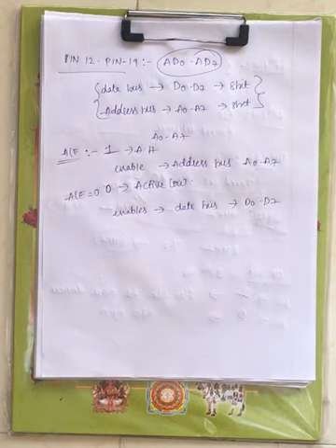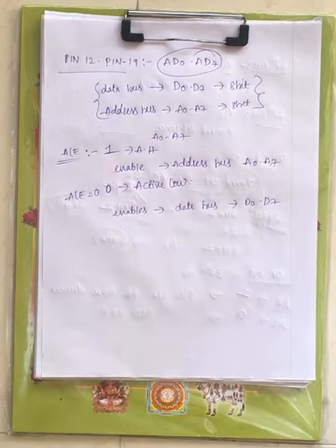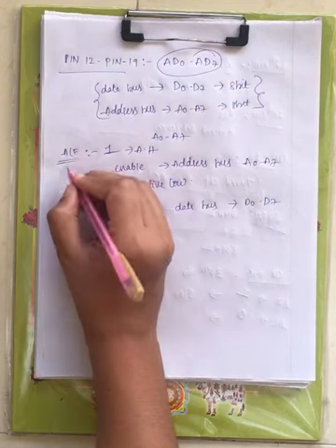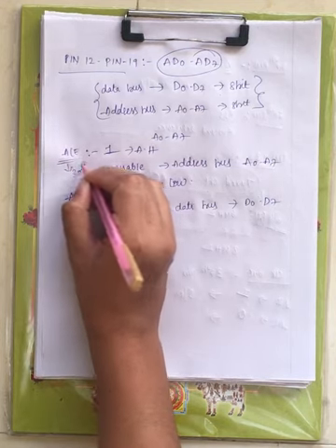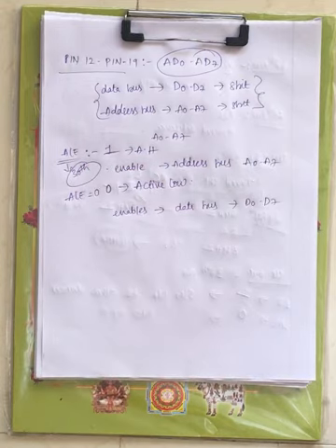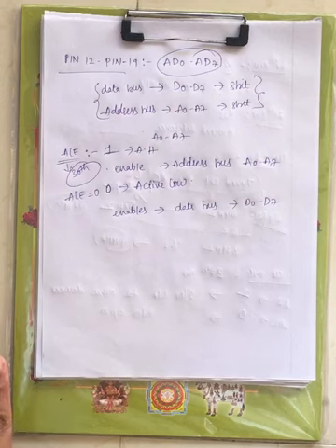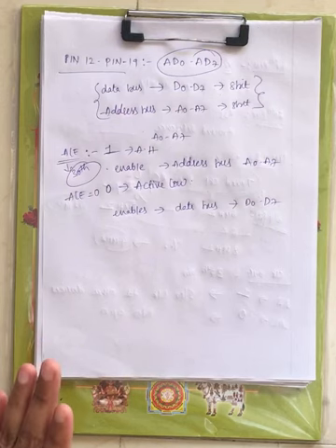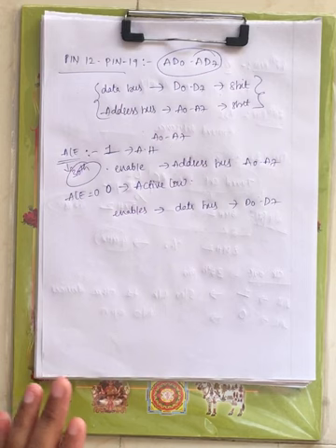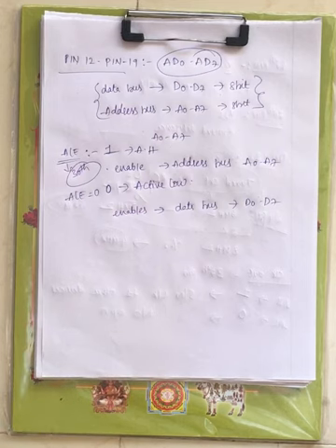Through this ALE only we can decide whether AD0 to AD7 carry address or data. ALE is provided at your 30th pin. From pin number 12 to pin number 19 we have AD0 to AD7, that is the 8-bit data bus, and the other one is the lower order address bus, that is A0 to A7.